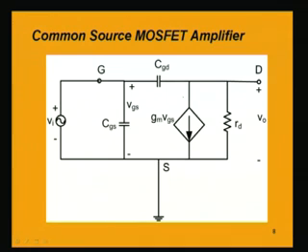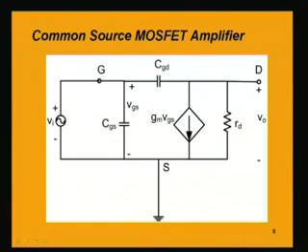If we can somehow bring this capacitance into either the input and output circuits or both by using some theorem, then we will be having easier analysis, because then the input and output circuits will be isolated, because this is the component, the capacitance between gate and drain, that is basically having a contact between the input and the output terminals.